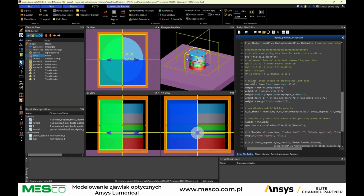So here we consider that all the dipoles have the same weight, in the sense that the emission of the dipole is the same whether you are at the center of the LED or towards the edge. That's not necessarily the case, but you can adapt that by changing the weight function here.